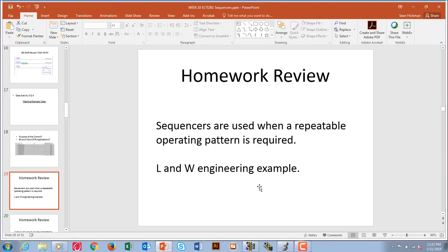And so you could see this on the HMI, that they just showed the sequence of the word. So it wasn't a very exciting HMI. All it had was a bunch of registers, double words with zeros and ones. The next one 0 to 1, next one 0 to 1. So that when the item actually failed and they had to try and figure out why it wasn't working, they could just look at the screen, and it showed what step of the sequencer it was on, which word on the control, and then they could see which items were supposed to be on. They could also look at the inputs and see which inputs were supposed to be on, and then that's how they troubleshot from there. And what this did is this didn't allow the operator to actually get into the PLC. They didn't have to have a computer, and they didn't have to look into the PLC at all, so they couldn't mess it up. All they had to do was look at the HMI, and the HMI replicated the status of the control words. Pretty interesting, huh?